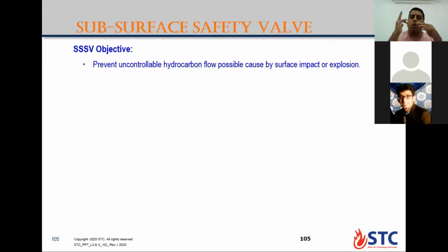That means when you cut the source of hydraulic pressure opening the valve and it drops to zero, the valve will close itself, preventing the flow from below in production. This is the main objective of the subsurface safety valve. Usually, the subsurface safety valve is mandatory in most offshore rigs and also in any wells near a population area, a city, or a camp. And also according to company policy.